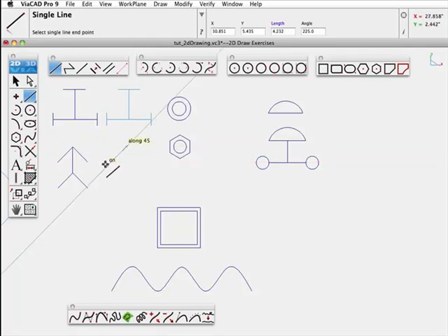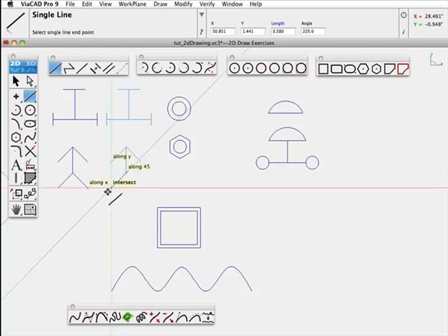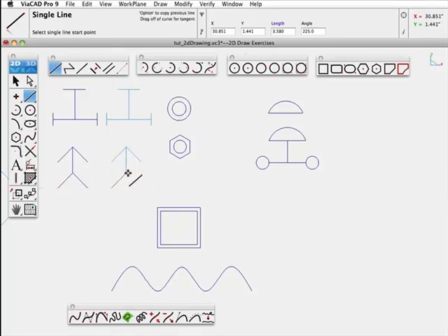The next graphic will be created of just lines and using the special alignment options that you learned in the Snaps tutorial. Remember, moving the cursor over a point as you drag sets that point as a reference point and allows you to align to it. Next, the circles.